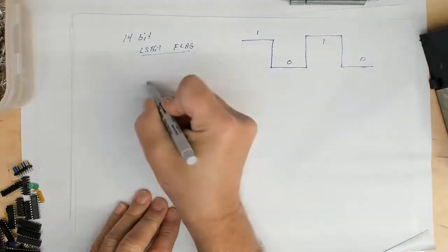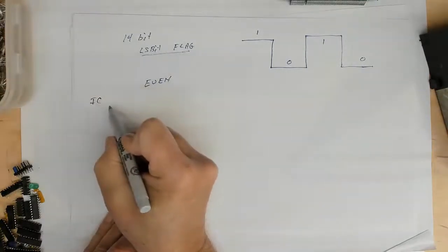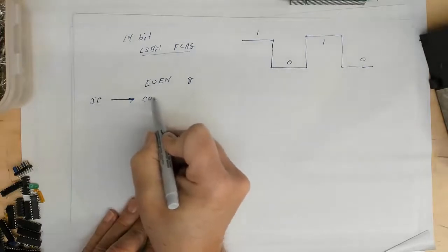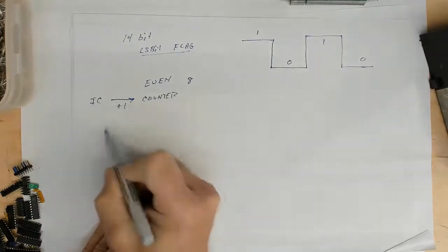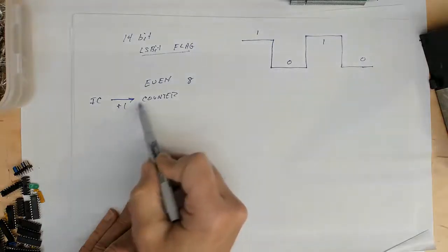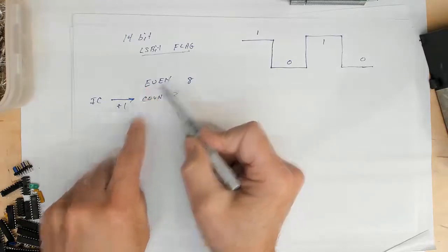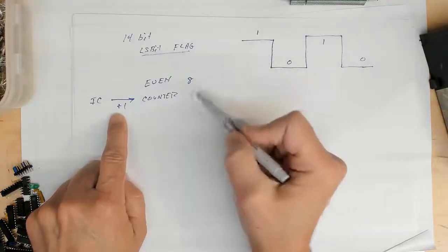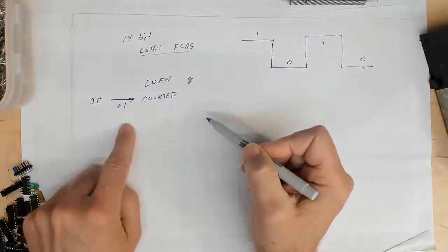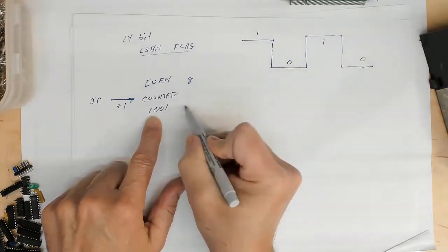Okay, so now let's look at what has to be happening if we do an even count. So we have our initial count, and let's say in this example we're going to do 8. When this goes from the initial count into the counter, they add 1 to it. So we take our initial count plus 1 to set that flag. You can say that they're just setting that flag to 1, or you can say that they're actually incrementing that count in order to set that flag. Because it was even, that bit was originally 0. Now we're going to set that to 1. We can either say that we incremented it by 1, or we just physically set that flag to 1. But at any rate, the value in the counter is 1 more than our initial count. That's going to look like a 1001 after we have added our additional number to it. Okay, so that's 9.